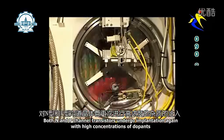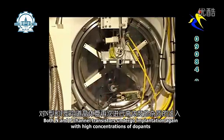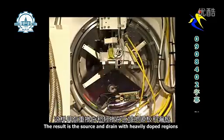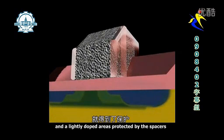Both N and P-channel transistors undergo implantation again with high concentrations of dopants. Arsenic is used for the NMOS transistor, while boron is used for the PMOS transistor. The result is a source and drain with heavily doped regions and a lightly doped area protected by the spacers.